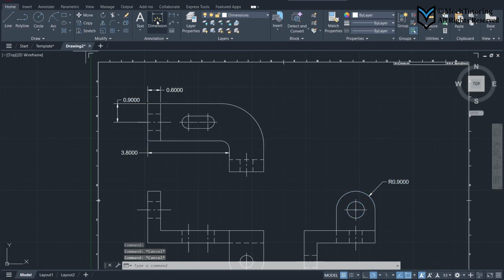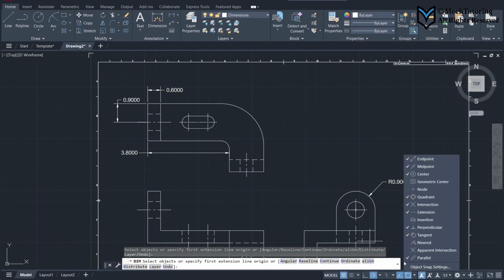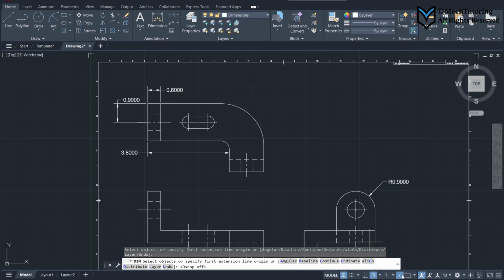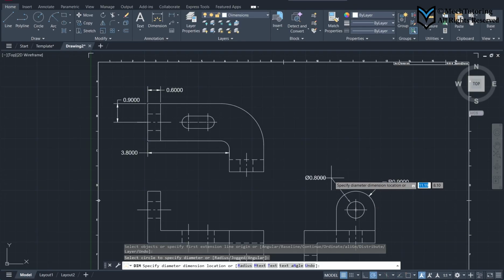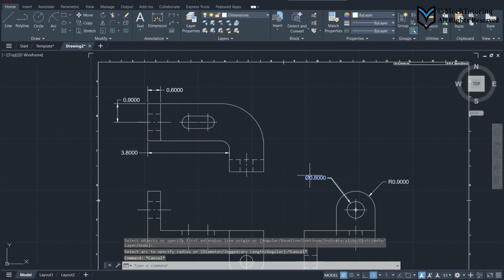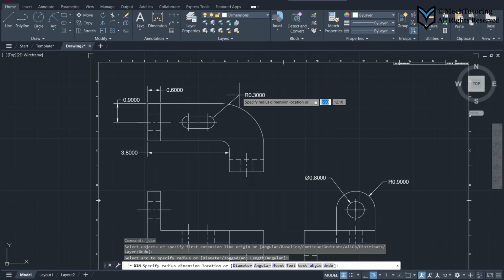And then I will dimension this hole. I'll turn off all of those, because I told you before they were gonna cause problems, okay? In dimensioning, always turn them off, okay? So now this hole is also dimensioned. So don't dimension it in the top view now, okay? For the slot, I'm gonna say this is the radius of the slot.